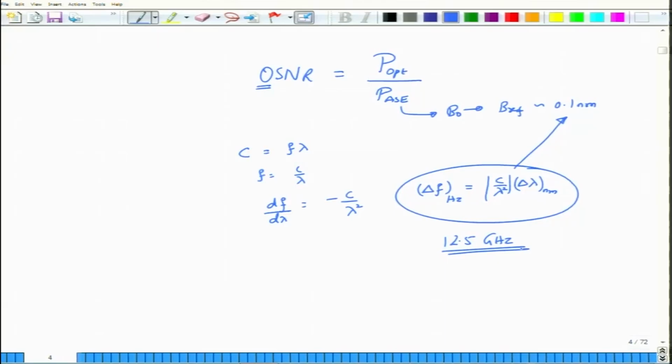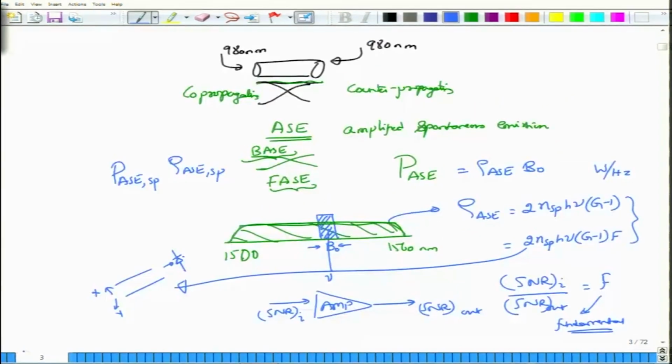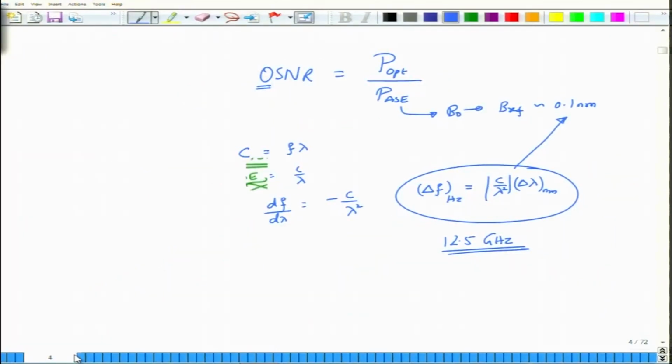So this is about the erbium doped fiber amplifier that I wanted to discuss, and what you will see is that these erbium doped fiber amplifiers can be used in three different ways. One at the transmitter itself. So this is the transmitter and then you keep an amplifier right away here. This arrangement is called the main amplifier or sometimes the booster amplifier.